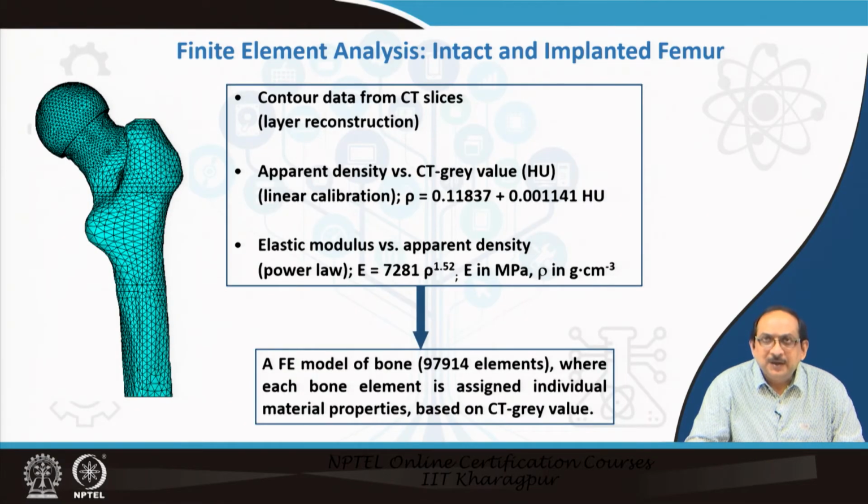Let us discuss the first topic of this lecture, finite element analysis of intact and implanted femur. Now, the finite element model of the intact femur was based on a CT scan data set of a subject. The solid model of the femur bone was based on the contour data from the CT scan slices using the layer reconstruction method.